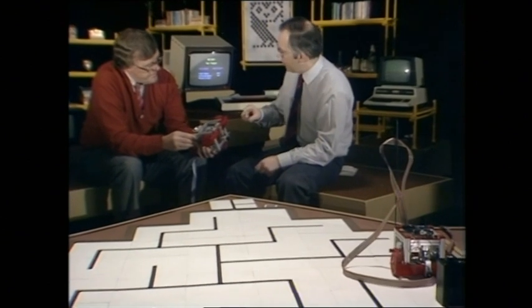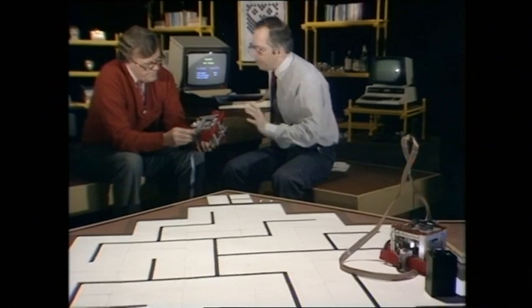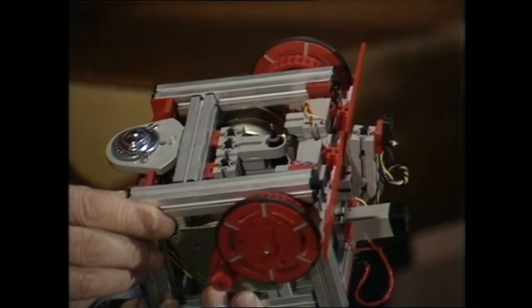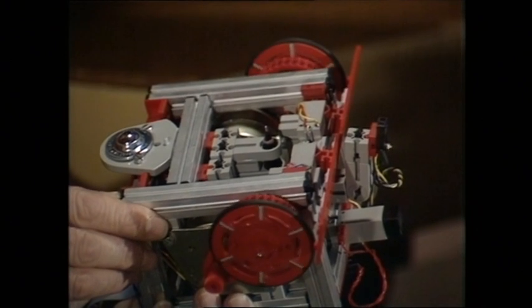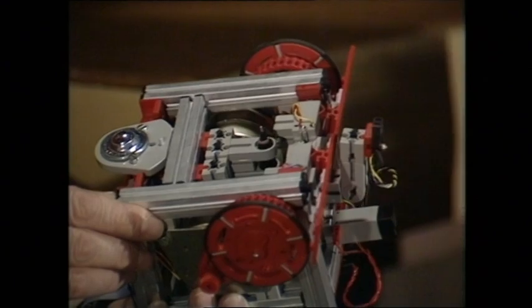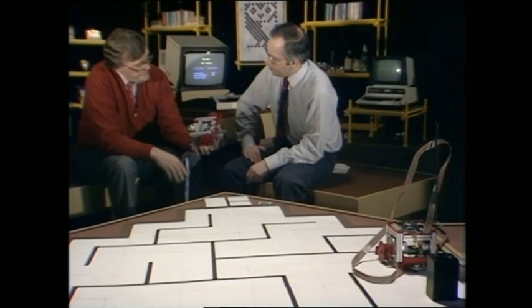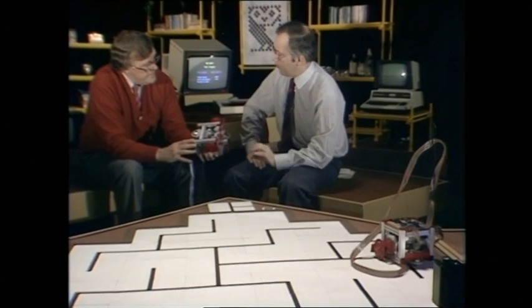Now, if I make the buggy move forwards by pushing that key, you see both stepper motors go in the same direction. So the buggy moves forward. If I say to the buggy, go left, then one stepper motor goes forward and the other one goes backwards to make it go round in a circle. And the pen there is just to trace its path on whatever it's cruising. That's right, and there's an electromagnet which lifts that pen up and drops it down. A digital signal, again, controls that.